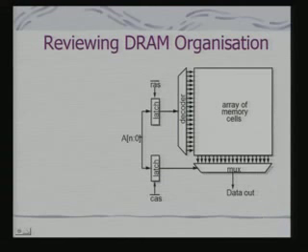So, it is not that ROM access would make the processor always suffer 4 wait states. It is indicating through memory request that it is now going into a memory access cycle. So, that memory access part of it can wait because it is accessing the ROM. So, let us look at the DRAM and the question of interfacing DRAM with ARM.